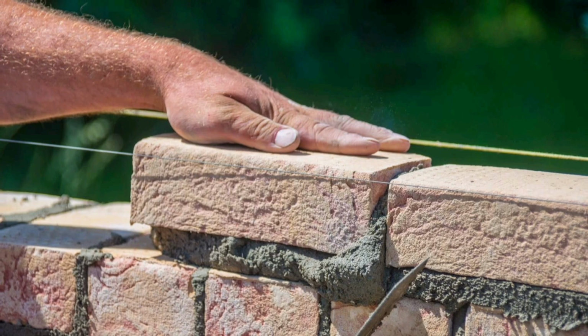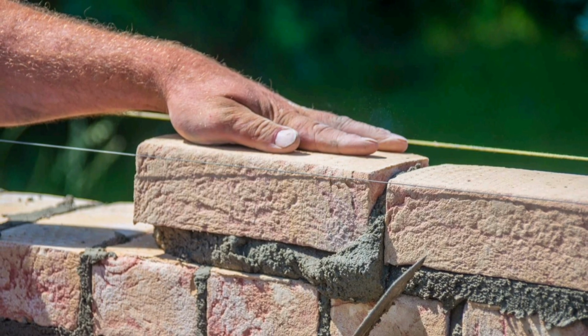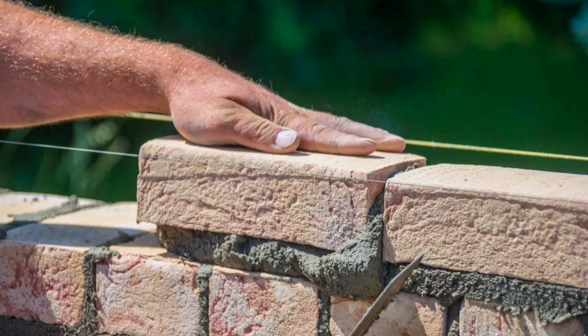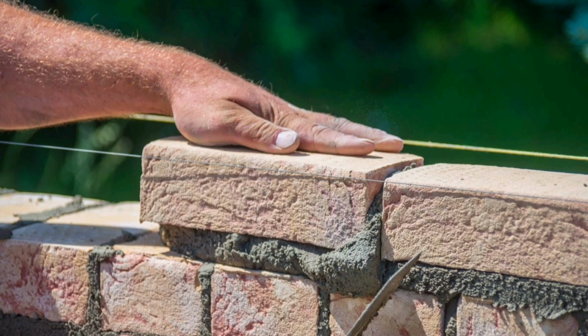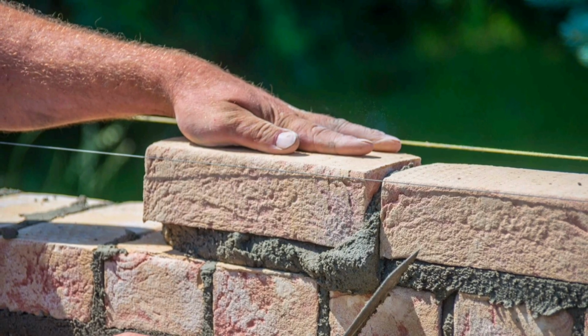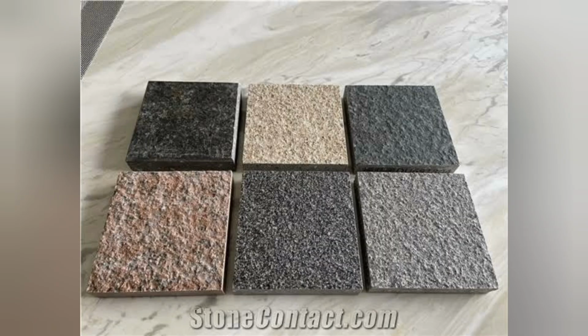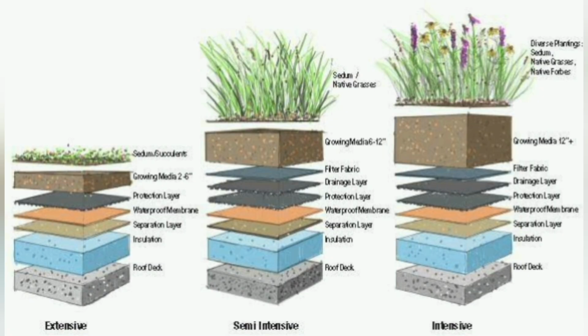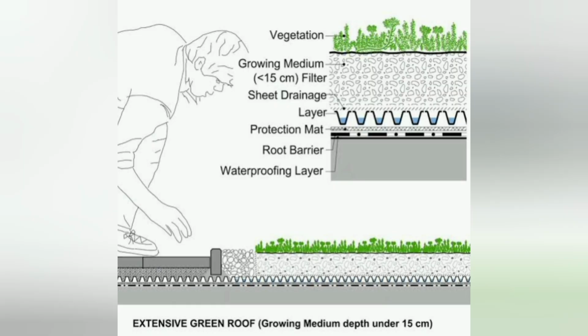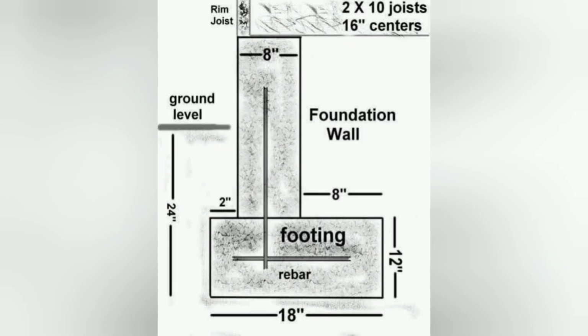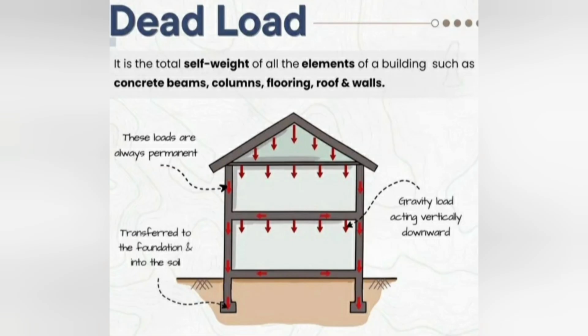A pro tip from seasoned structural engineers: always do a realistic dead load estimate early in your design. A common and costly mistake is for architects to assume lightweight construction and then later specify heavy granite floors and massive green roof systems without communicating this to the structural engineer. This can lead to under-designed foundations and beams, requiring expensive redesigns. The dead load is the constant baseline upon which all other loads are added, so getting it right is non-negotiable.